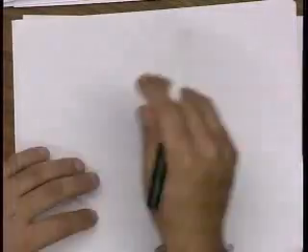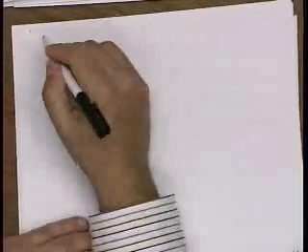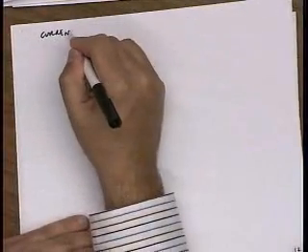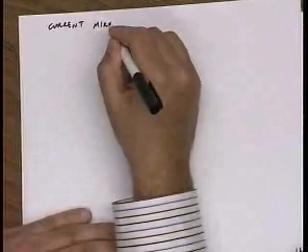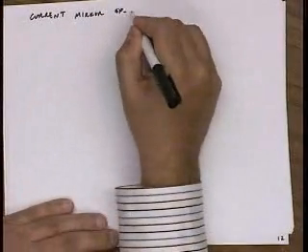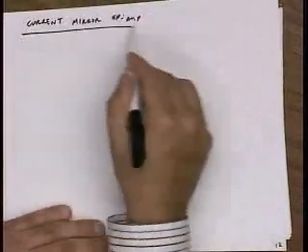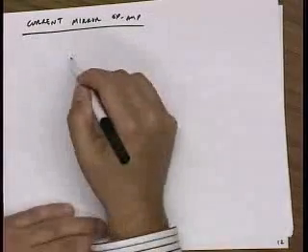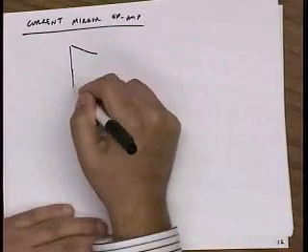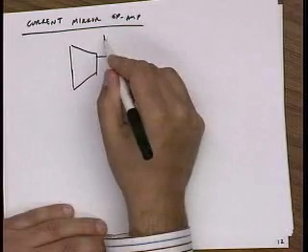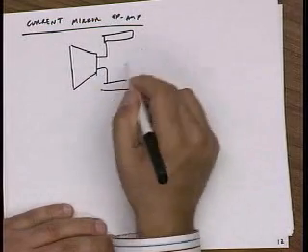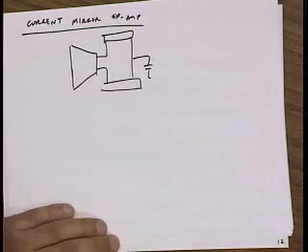Okay, let's look at some other amplifiers to give you some more ideas for your project. A very similar op amp is called a current mirror op amp, and it's actually just what we talked about. There's a GM stage, and then you have mirrors, and you dump it to the output.